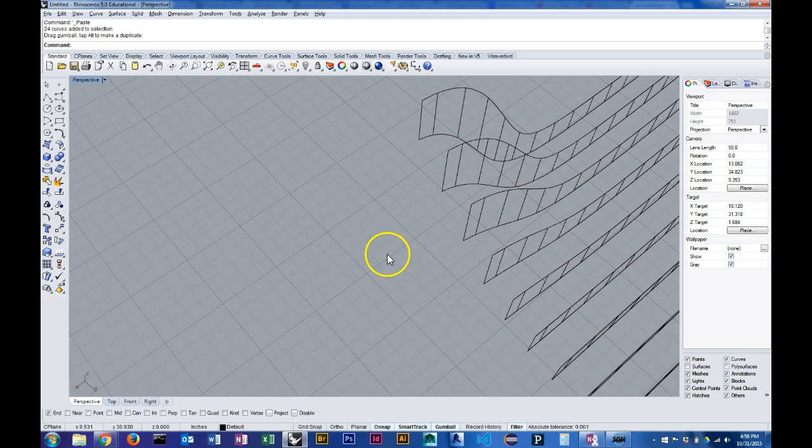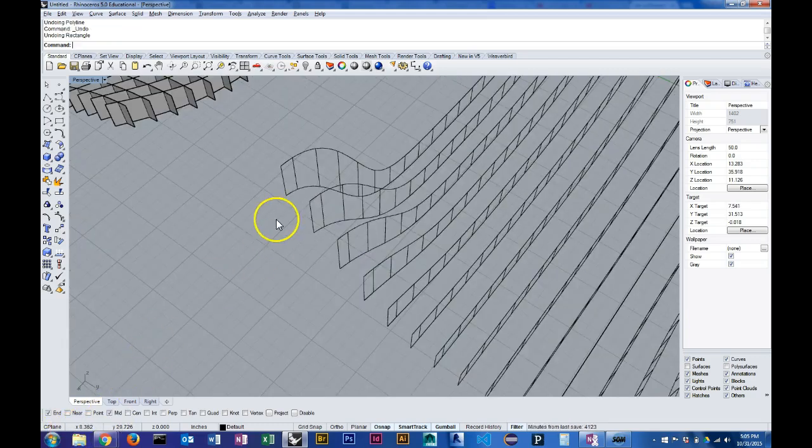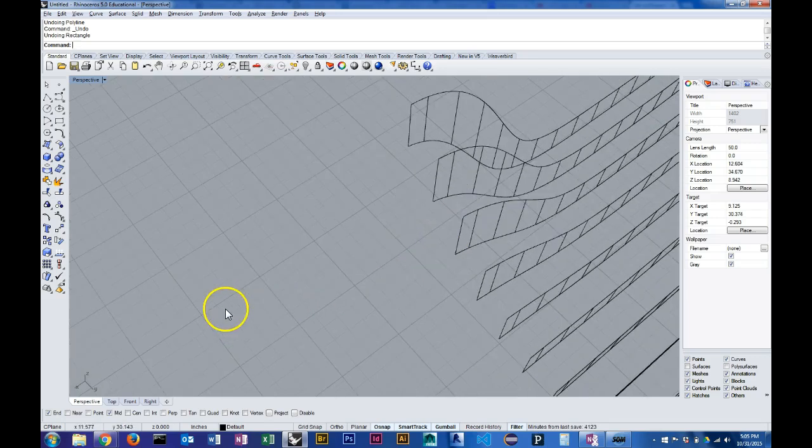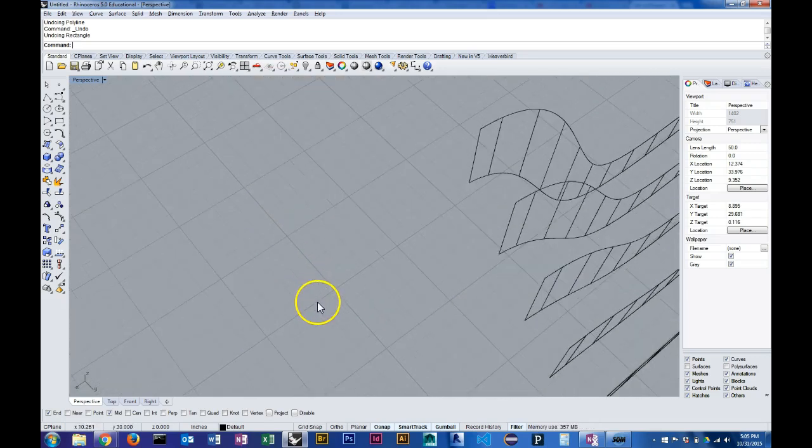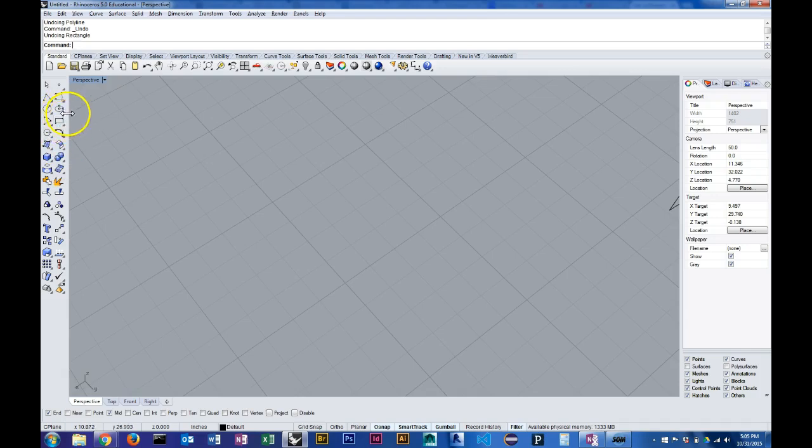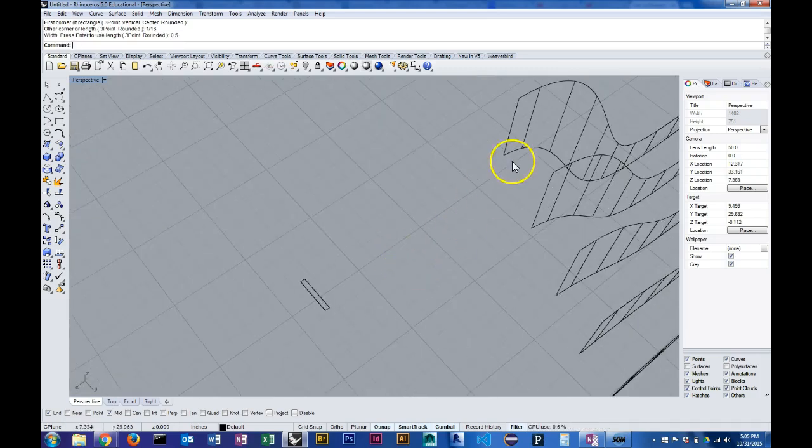But my material thickness is not going to change. So what I can do is model the notch that I'm going to use at each of these intersection points. And that's really simple, and I'm actually going to make it larger than the notch. I'm going to have one dimension be 1/16, which is my material thickness. But then the other one, instead of 1/4 of an inch, I'm going to say 1/2 of an inch. And the reason I'm doing that is because of those places where halfway is more than 1/4 of an inch away from the edge.